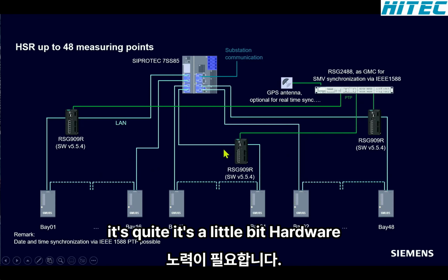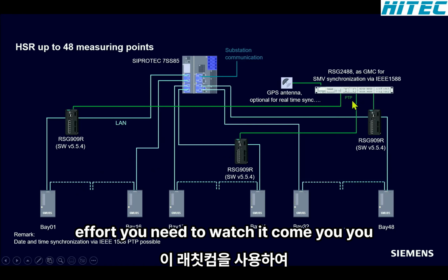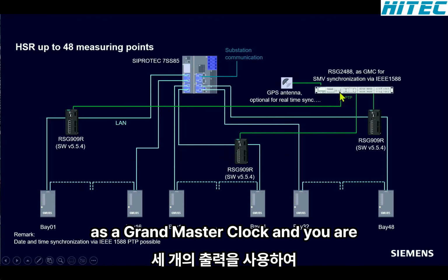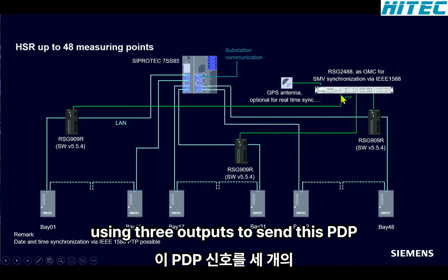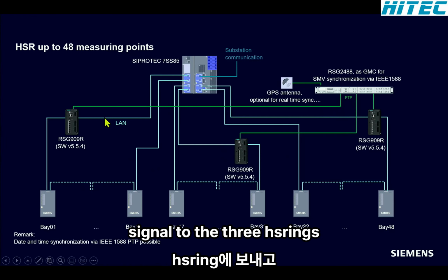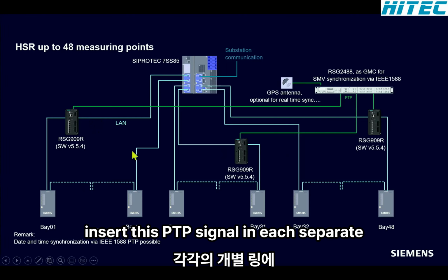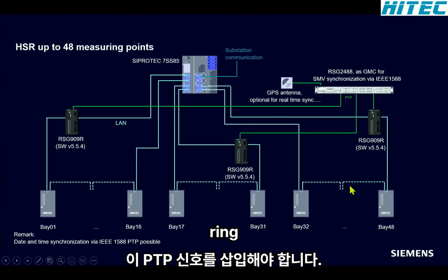It's a little bit more hardware effort. You need this Ruggedcom, and you configure it as a grandmaster clock. And you are using 3 outputs to send this PTP signal to the 3 HSR rings. And then via a red box, you have to insert this PTP signal in each separate ring.